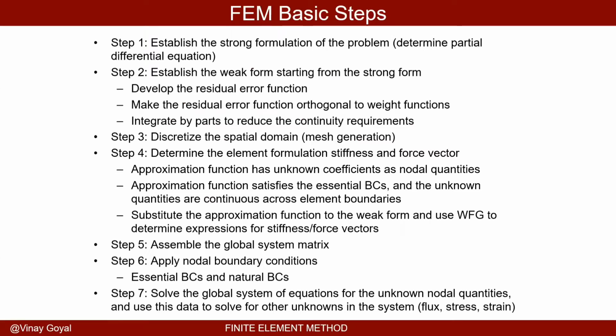So what are the finite element steps that we want to establish? First, we want to establish the strong form of the problem. So basically, what is a partial differential equation that describes the problem of interest? We want to then establish the weak form from the strong form. Starting from the strong form, we want to reduce the continuity requirements. And from there, we can develop first the residual error function, make the residual error function orthogonal to the weight functions, and then integrate by parts so they can reduce the continuity requirements.